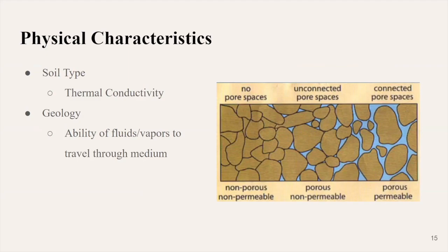soil type, depending on the thermal conductivity, it can be difficult to heat the ground to the correct temperatures. One of our treatments is thermal conduction, so that would be a major issue. Would not suggest using that one. Next is geology, so the ability for the fluids and vapors to travel through the medium to be removed. Things like porosity and permeability could play a major factor in whether a specific treatment is worth it or not, and actually able to work.